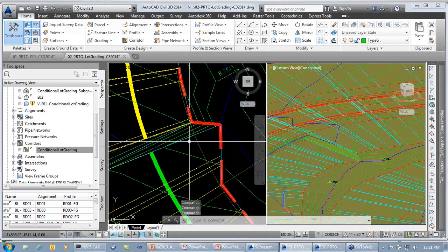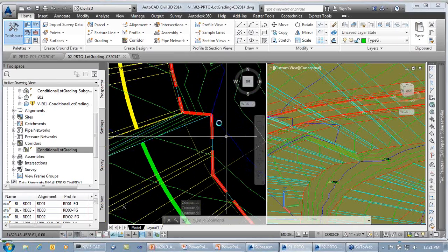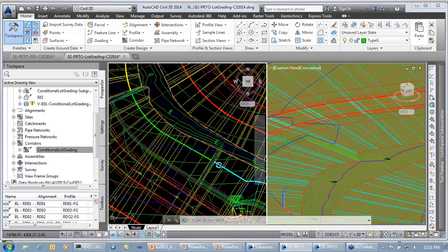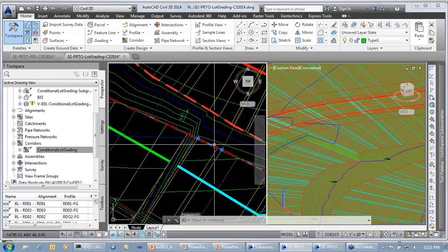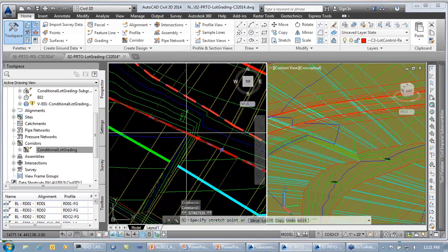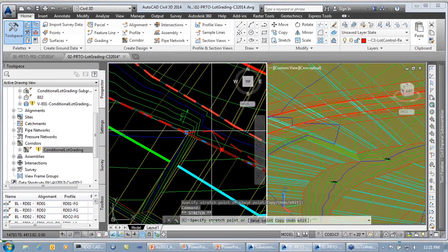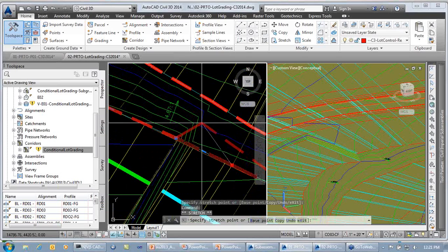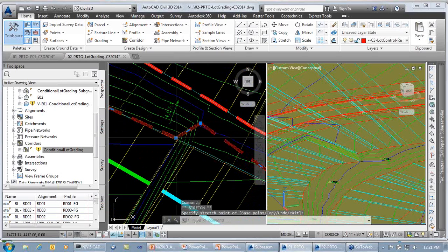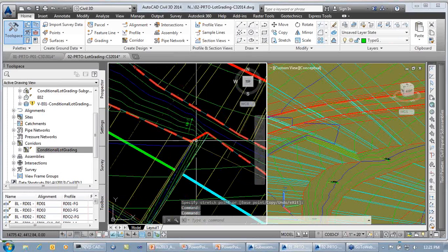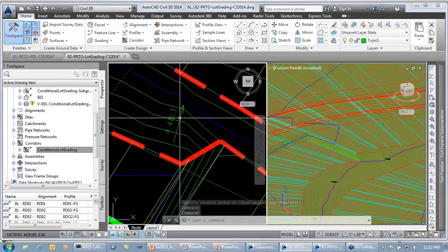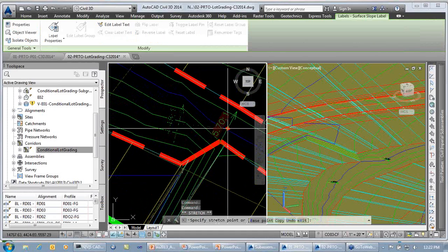Yeah, so now I can get these contours to wrap around, so I can kind of play with that, maybe do the same thing down here where I transition from the B's to the G's, or excuse me, from the walkouts to the gardens, and again, just kind of eyeball where that lines up with the end of slope, hit the rebuild. All right, and we'll see again, see if I can get a little bit better looking set of contours there. I do have my slope labels in here so I can test and see as I move this along.